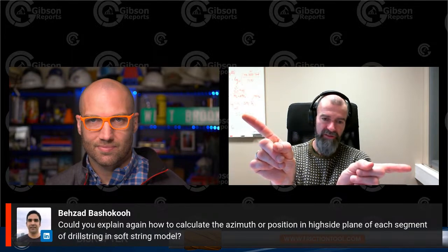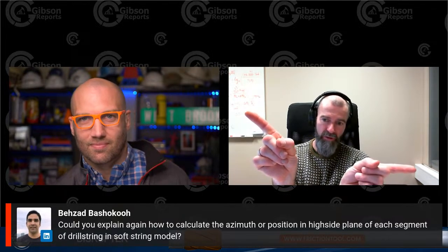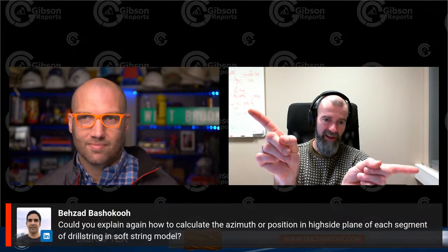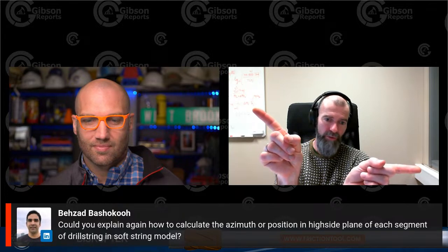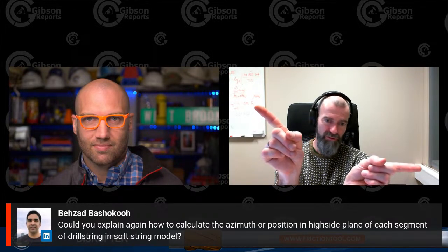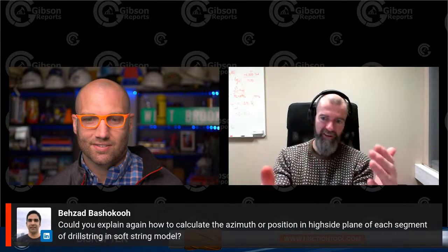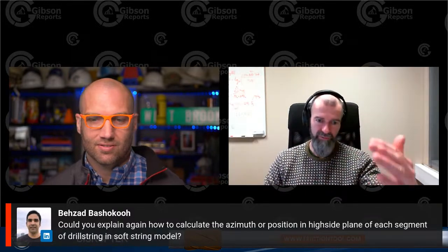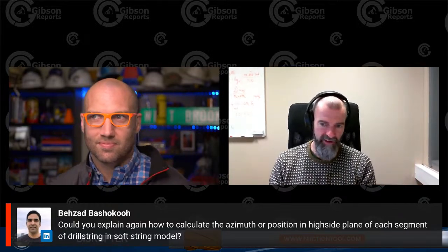Then you can just take those two vectors and add them together. That means you get a new vector. It has a direction. If the magnitude of that vector is bigger than the weight, basically gravity times mass, then you know it will move. So you use those two vectors, and then you can calculate where it moves, and it will be restricted by the inner circumference of the hole. So it'll just move to one or the other direction. Basically, it's Newton's first law.